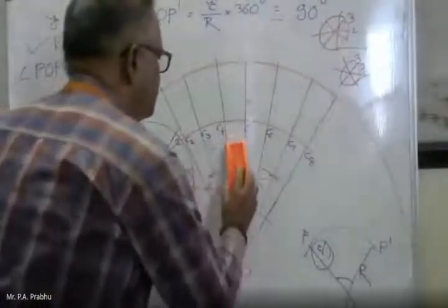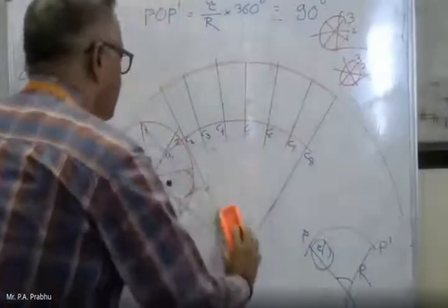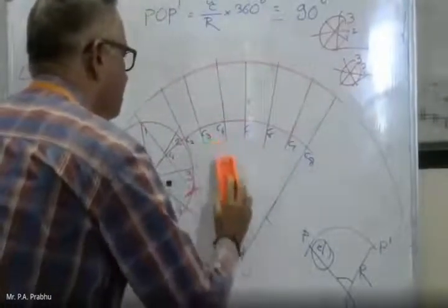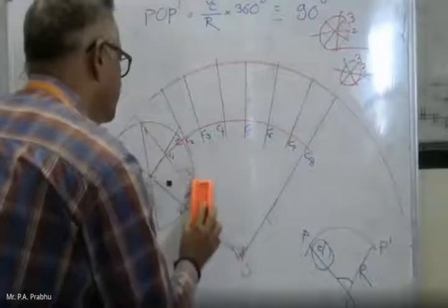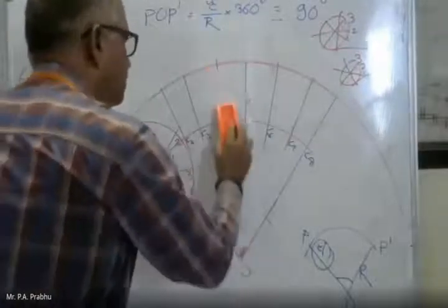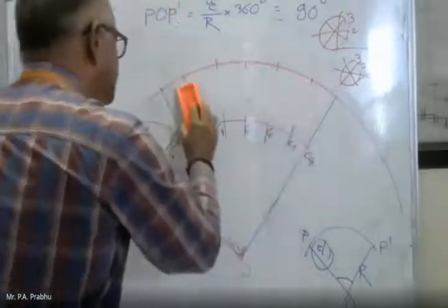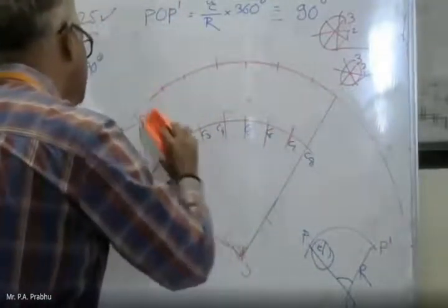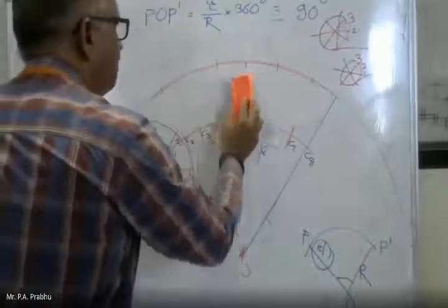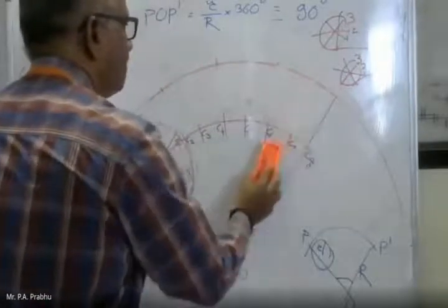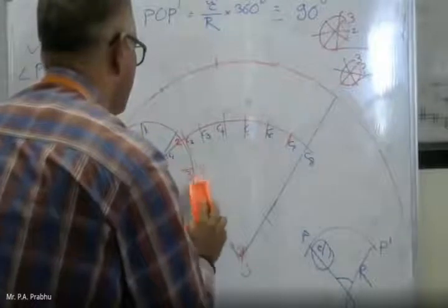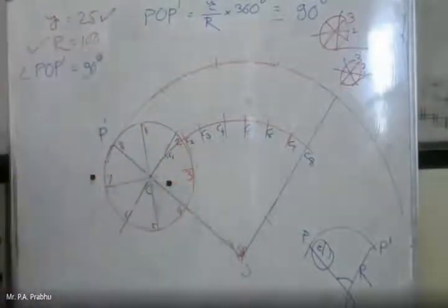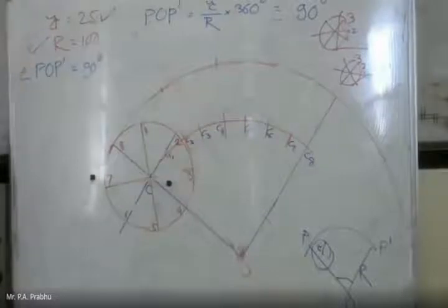Now I am erasing a certain part. But in your drawing, keep it with a faint line. Don't erase the total. This is called the constructional part. It must be seen with a faint line, remember. So we have found the locus of center C.